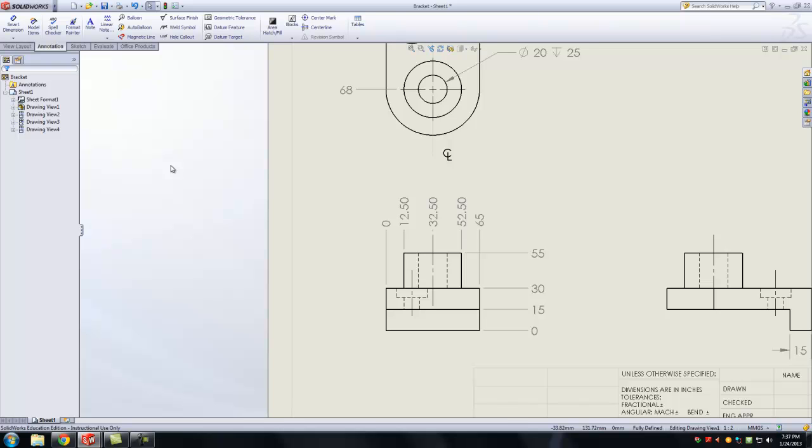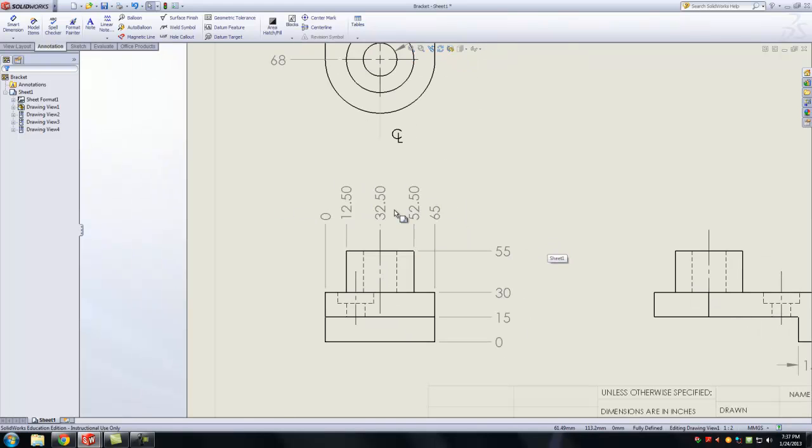Any questions on this? Yeah, if we are going to do it, would we have to change the text? Good question. So for horizontal ordinate dimensions, the text has to be this way. Because otherwise, imagine this text is turned and this text is turned, they won't fit on each other. Okay, so it's okay just for, in this case, to have the text vertical. Nathan, you had a question? No, that was actually. Okay.